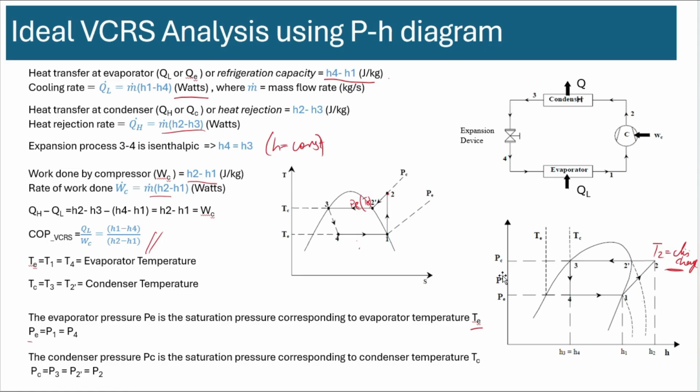But one of the first things that deviates from ideal process to real process is it may not be exactly coming in at the phase change line. It might go a little bit towards the left. Okay, so it might be doing a little bit of subcooling.